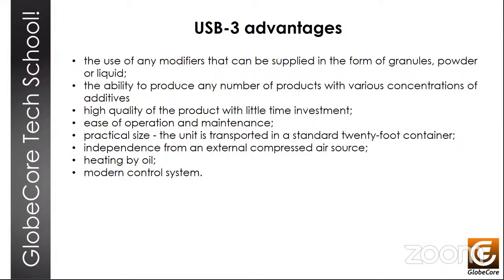The intermediate tank is designed for preliminary mixing of the polymer with bitumen, and it increases the bitumen polymer contact time, which takes some of the load off the mill. The tank itself is equipped with a high-speed agitator, which allows mixing the bitumen and polymer evenly. The level sensors are installed in the tank to maintain a constant level of bitumen for optimal mixing conditions.